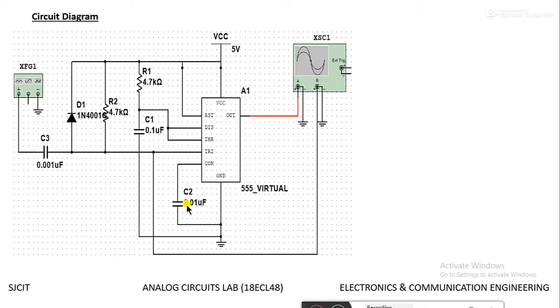a capacitor of value 0.01 microfarad is connected across control to ground, and then VCC and reset are connected to VCC 5 volts.